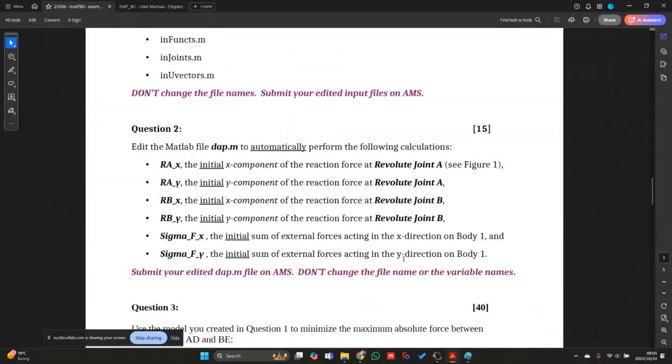Right, so I think this was then, yes. Sorry, which forces? Yes. No, so you'll need to still account for that. So that's essentially why when we calculate sigma Fx and sigma Fy, we include the friction forces over there. The reaction forces itself is just focused on the actual joint itself. So you still need to account for the external forces when you do that calculation.